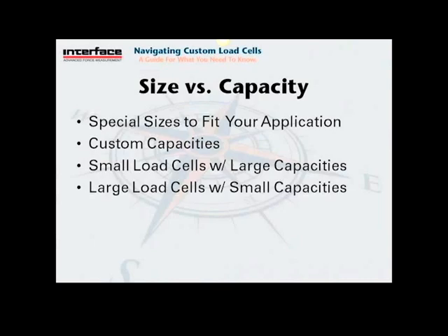Works great in the 10K and 50 kilonewton capacity. As you start to push beyond those limits up into maybe 11.5, 12K, then the performance begins to suffer because components of it begin to bend instead of working in shear. So large load cells for low capacities generally won't have very much output, or they become very fragile if you have large masses in a very small gauge area in order to get the output that you need.